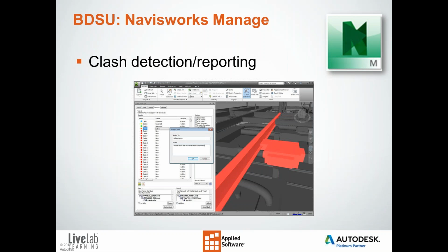If I have time towards the end of this webinar, I'll bring up Navisworks and give you a live example of that. We can check as-built laser scan data against 3D designs. I can view clashes in context with geometry in the model and in relation to other clashes. And if I want to view my clashes, I can make all non-clashing items transparent to more easily locate them in the model.